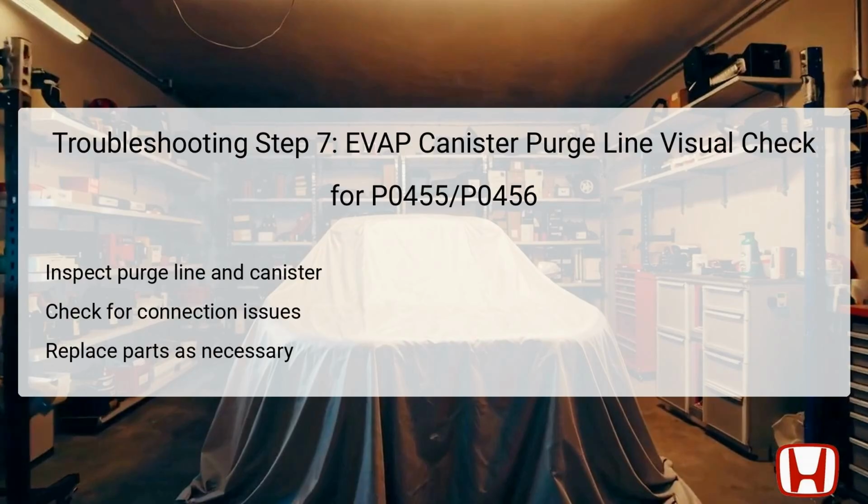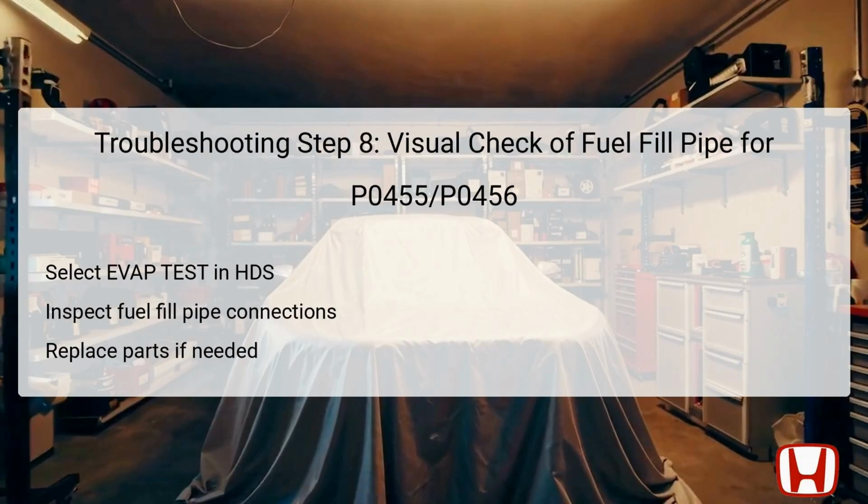It's critical to ensure that all lines and components associated with the canister are intact to allow correct vapor flow and pressure management. Diagnosing and rectifying any issues here is vital for the overall performance of the vehicle's emissions control system. For the eighth step, utilize the HDS to conduct another EVAP test to ensure that both the fuel fill pipe and vapor recirculation tube are functioning correctly.